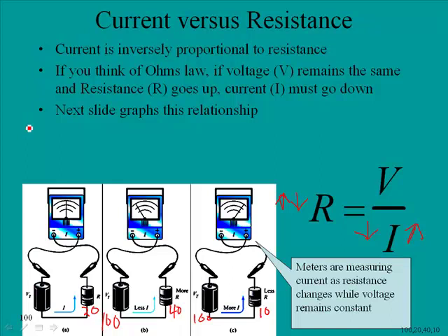So here we start out with 100 volts and 20 ohms, and that will give us 5 amps of current. Then we're going to leave the voltage the same and increase the resistance. According to Ohm's law, they're inversely proportional, so the resistance was 20, it goes up to 40, so there should be a decrease in current. If we do the math, we get about 2.5. So resistance went up, current went down, and here we're going to drop the resistance dramatically.